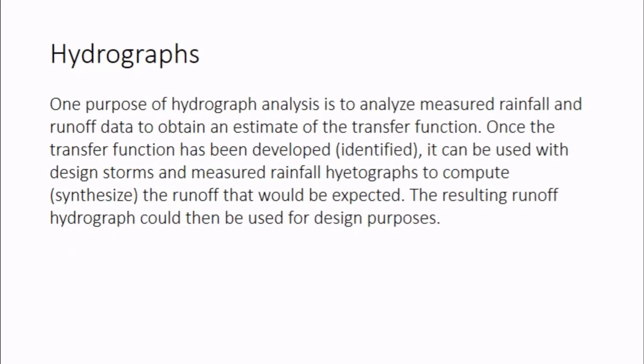So, ano ba yung hydrograph? One purpose of hydrograph analysis is to analyze measured rainfall and runoff data to obtain an estimate of the transfer function. Once the transfer function has been developed or identified, it can be used with design storms and measured rainfall hydrographs to compute or synthesize the runoff that would be expected. So, the resulting runoff hydrograph could then be used for design purposes.